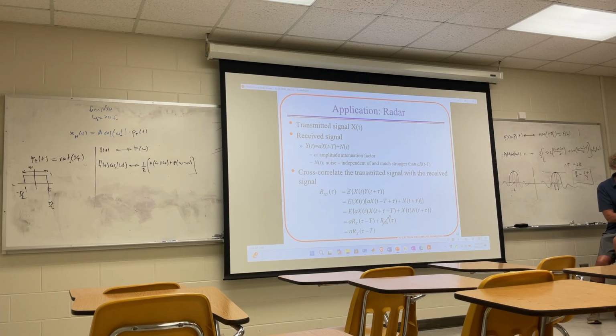So when we do a cross correlation function related to signal processing and a radar signal, after all is said and done, when you have the correlation between the noise, you're basically going to get an autocorrelation right here. Noise, see x of t, n of t plus tau. That function is gone. It doesn't exist. Remember, the mean value of noise is 0.